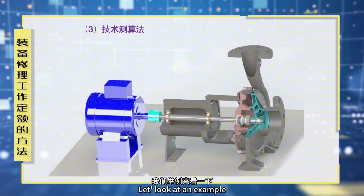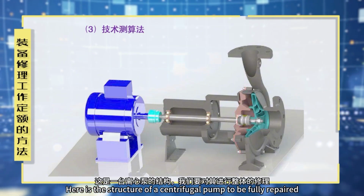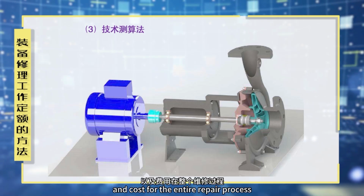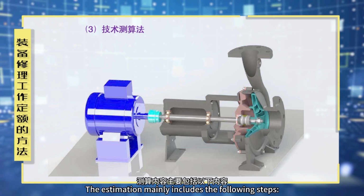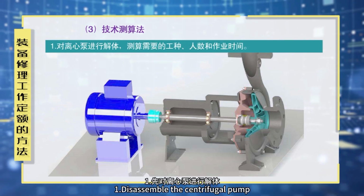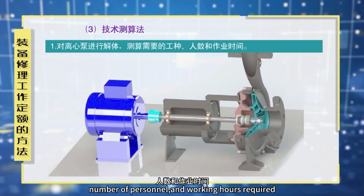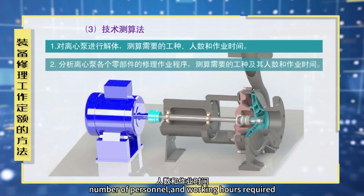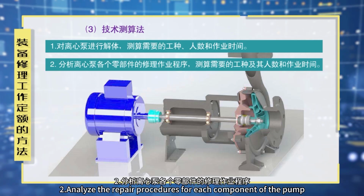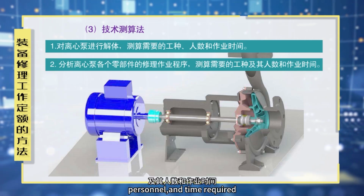Let's look at an example. Here is the structure of a centrifugal pump to be fully repaired. We need to determine the total personnel, working hours, and cost for the entire repair process. The estimation mainly includes the following steps. First, disassemble the centrifugal pump. Estimate the types of workers, number of personnel, and working hours required. Second, analyze the repair procedures for each component of the pump, and estimate the worker types, personnel, and time required.